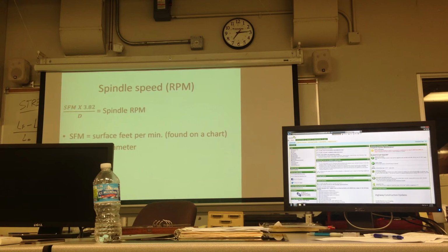And if you're going too fast, that heat won't eject in that chip. The heat will be stuck in the material, it'll be stuck in the tool, something will break, right? If you're going too slow, usually the problem is the heat isn't ejected quickly enough and the tool will start rubbing. And it's bad for tool life, really, if you're cutting way too slow. But that depends on your feed rate as well. So you can usually get away with cutting too slow, but it's not recommended. A lot of guys who are very new to machining are like, oh, I'll run really slow and I should be fine, but then they break their tools.